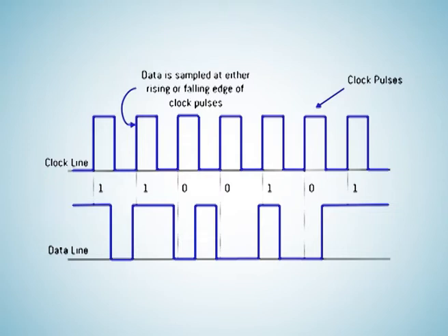The receiver clock follows the sender's clock. Whenever the receiver clock has a rising edge, the receiver node anticipates a new bit arrival and captures the state of the data line by storing it as a bit in the shift register. The speed at which the data transfer takes place, or data rate, is completely decided by the sender's clock frequency, and the receiver has no control over it.